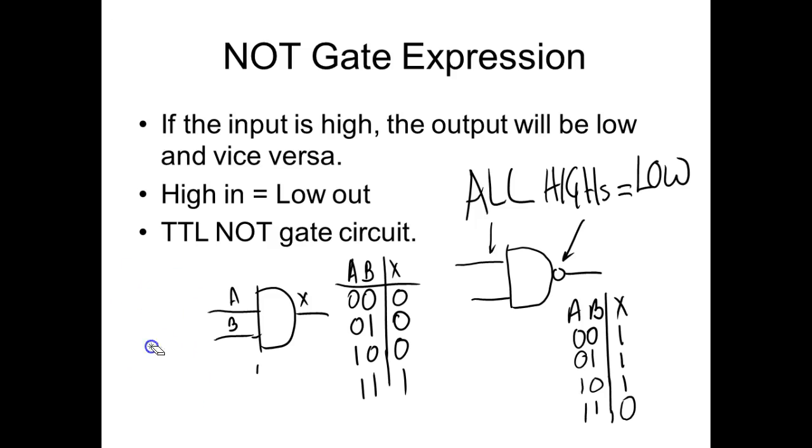Yeah, later on we're going to learn those symbols. First of all, we're going to learn these guys right here, and then we can understand those. So what I'm doing is I'm looking at bubbles. If I don't have bubbles, then they're true when they're high. If they do have the bubble, then they're true when they're low. So here we look at this symbol.